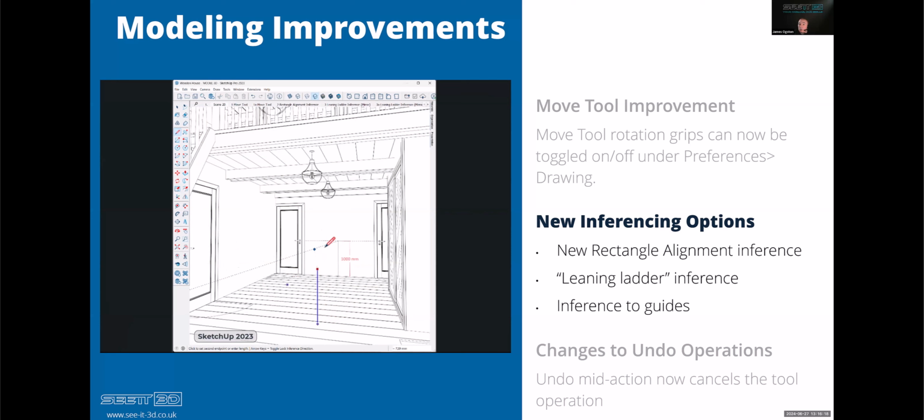You'll notice that it's not finding that guideline, okay? Doesn't find it. You may think it does, but it doesn't. You would have to find an intersection point or draw a marker line along the guideline to make that work. And as you see, I'm thinking that I've drawn it correctly, but the line is small. It's 300 odd millimeters in height, drawn out from the wall perpendicular along the green axis. Again, it is not finding the guideline.